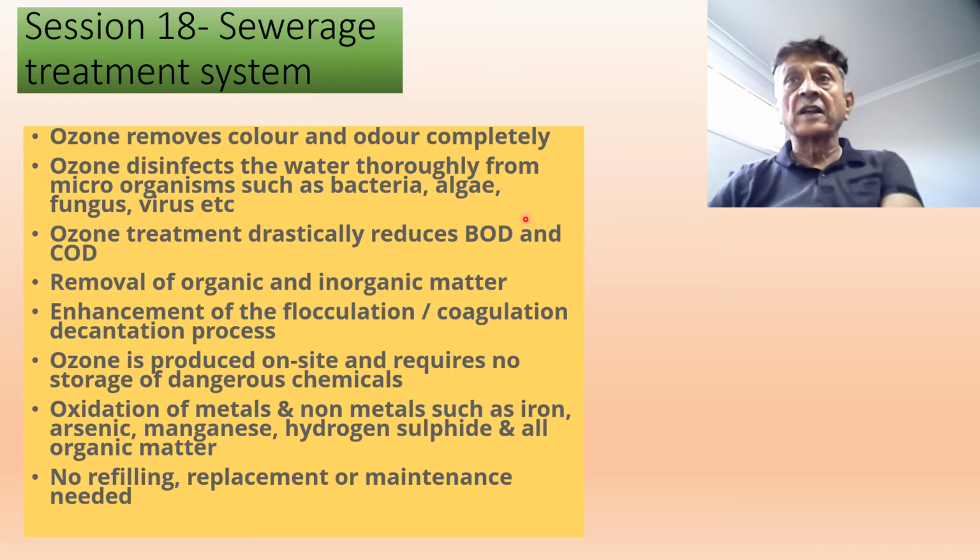Ozone treatment also reduces the biological oxygen demand and the chemical oxygen demand. The biological oxygen demand is increased by proteins that can be oxidized or digested by bacteria. So after the digestion, we use ozone treatment to remove the protein material of the bacteria. Of course, ozone reacts with quite a number of chemicals that can be oxidized, and therefore the chemical oxygen demand is also reduced.